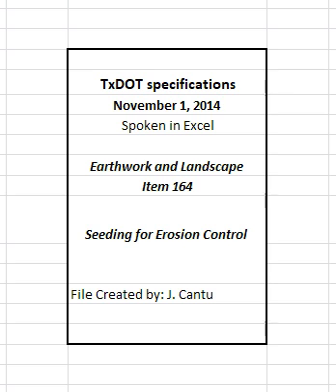3. Construction. Cultivate the area to a depth of 4 inches before placing the seed unless otherwise directed. Use approved equipment to vertically track the seed bed as shown on the plans or as directed. Cultivate the seed bed to a depth of 4 inches or mow the area before placement of the permanent seed when performing permanent seeding after an established temporary seeding. Plant the seed specified and mulch, if required, after the area has been completed to lines and grades as shown on the plans.